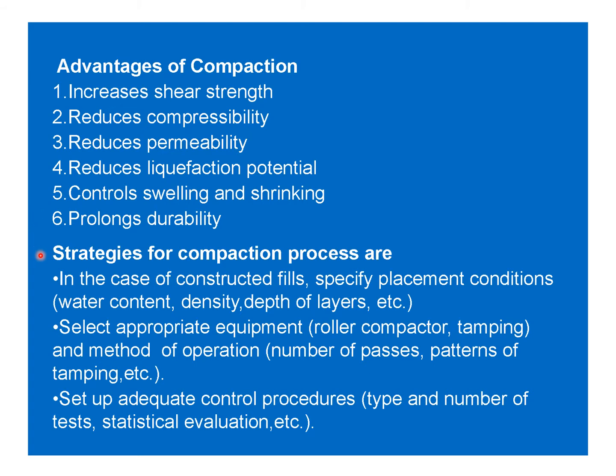Now, strategies for compaction process are: in the case of constructed fills, specify placement conditions, that means water content, density, depth of layers, etc. Select appropriate equipment, roller, compactor, tamping, and method of operation, number of passes, pattern of tamping, etc. Set up adequate control procedures, type and number of tests, statistical evaluation, etc.